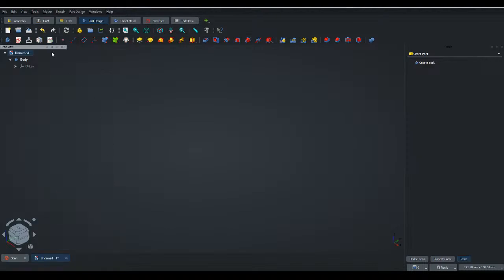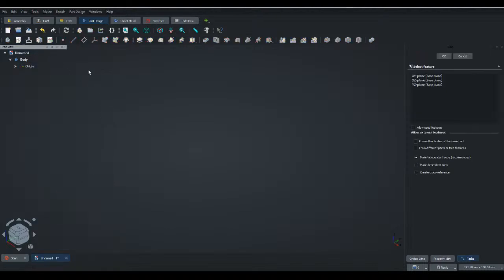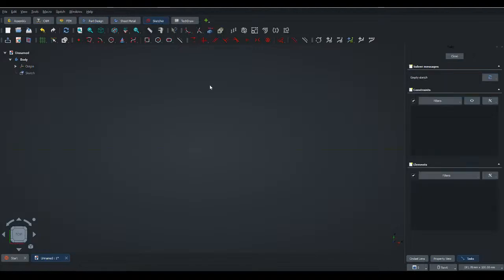Double click on the sketch and then see if you can turn it on. New sketch. XY plane. Then click OK. I'm looking at what these other settings do. Okay, click OK. Are you zoomed in too far or too far out? No. Okay. So, okay. I want to make a line. So I click it. I have the line tool.